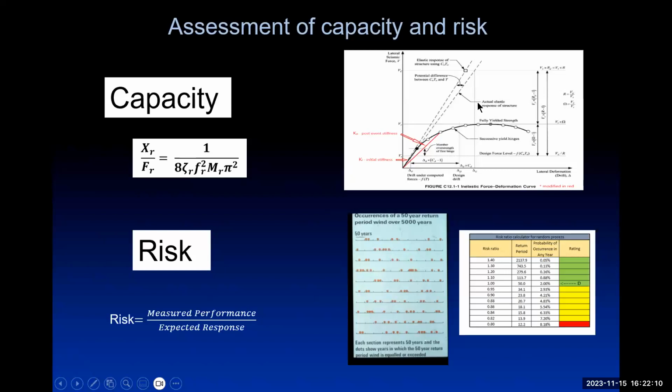So as we leave the linear elastic range, then we get ductility occurring, and we have to be careful with what happens here. But nevertheless, what does happen is that the linear elastic range characteristic will move, and it is possible to look for changes in that.